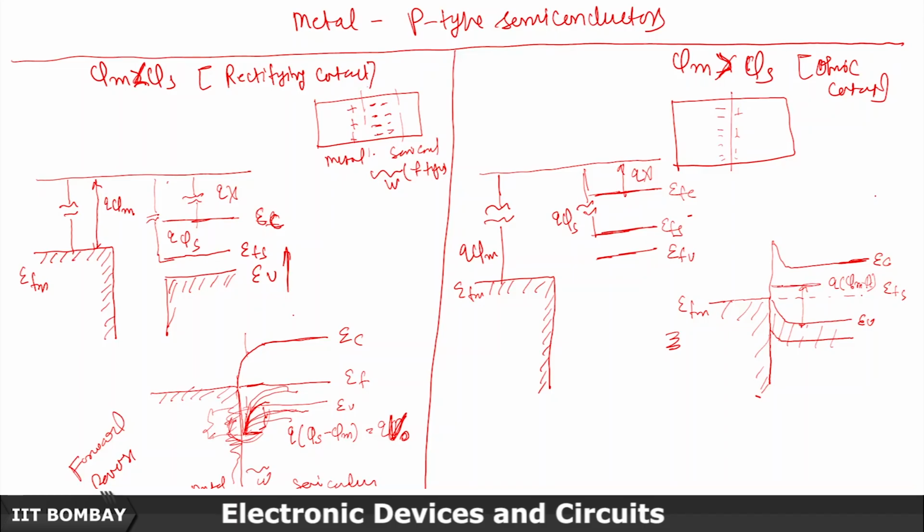So again, here there is no significant barrier potential from metal to semiconductor, and as you can see from these energy band diagrams, so again it will be band here and there, as we discussed in the previous case of metal to n-type semiconductor, and it will have the flow of electrons in both the directions, right, and it can have the current. So there is no such barrier potential here.